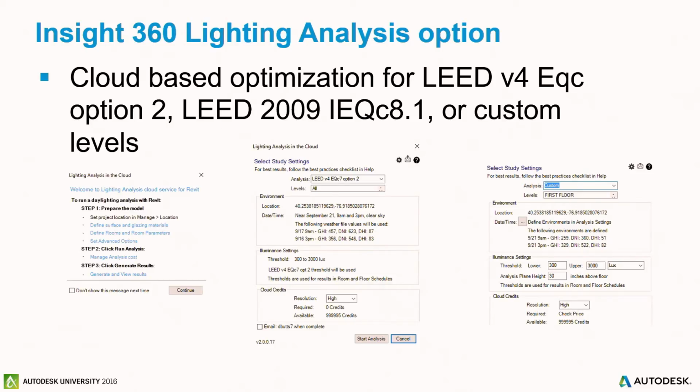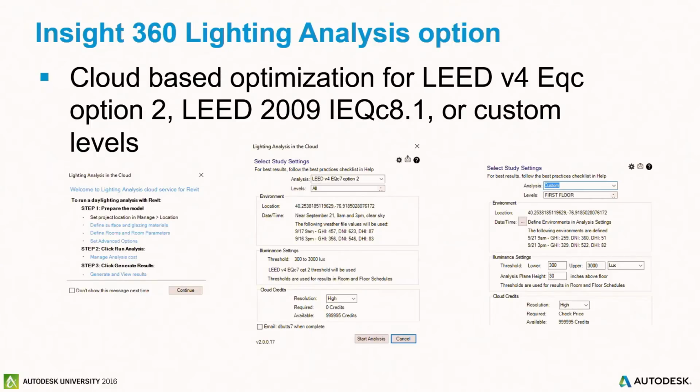Because this is a cloud-based tool, you can actually use cloud credits for this. In some cases, they're required. In some cases, they're not. So that's what Autodesk is doing, is they're making this a cloud-based tool that you can use the cloud credits that you get with your subscription. It's one of the options that you have for it. And it really doesn't take a whole lot. I've actually done some that you see this one actually says that it's 0 credits. It doesn't require any, even though it's a high-resolution model. Just depends on the size of the building and how much stuff that you have in here.